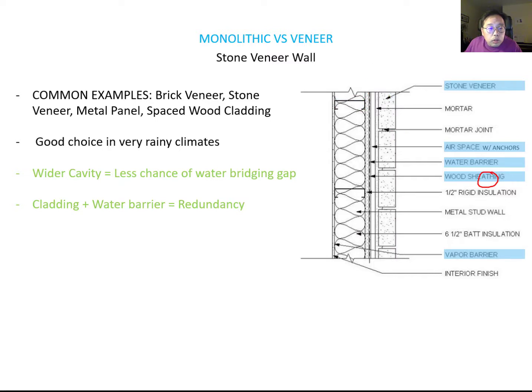Okay, I think you now have a better understanding of the system here. You can see the wall framing, the interior gypsum board, which is the interior finish wall, and the sheeting, which is the exterior cover board. To protect the cover board, you need the waterproofing membrane, and to increase the wall performance, you need to add the rigid insulation and then the cavity space. Remember the minimum cavity space thickness and the maximum cavity space; please look at the first lecture where I already covered that.